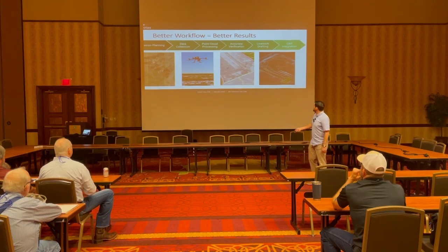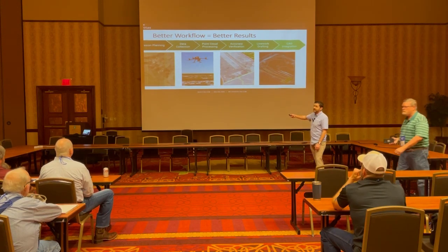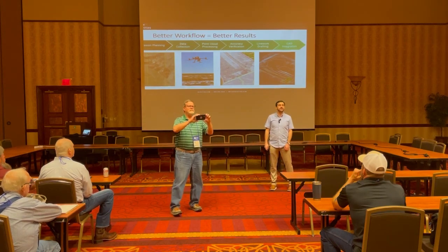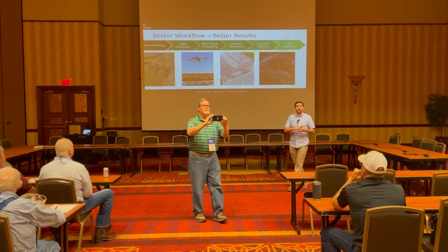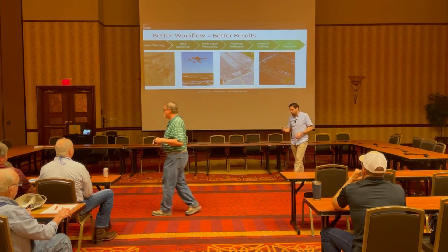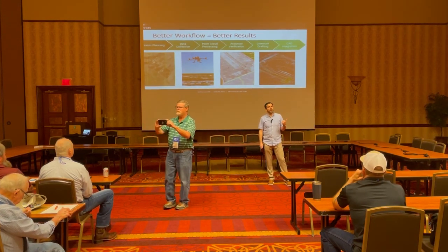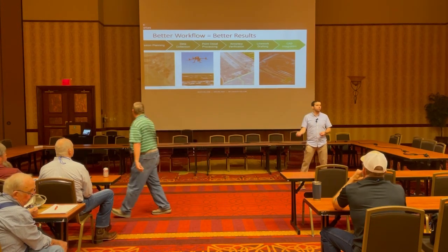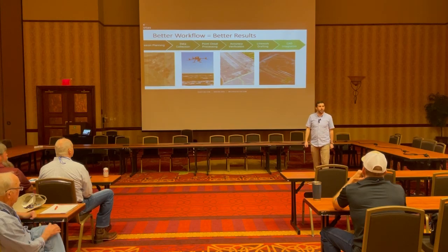That means the first step is going to be mission planning, the most boring, really simple, and really easy to forget thing that makes everything work so much better in the office. Mission planning is simple questions like, should you even fly a drone on this site? What altitude should you fly at? And where should I set control points? Or how many control points should I set?